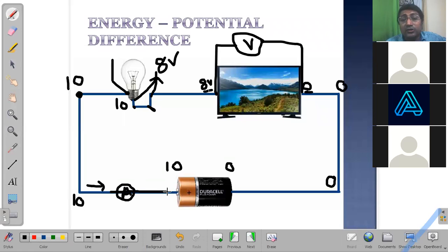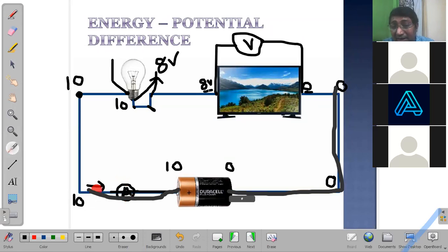Since I want to know, if you remember, the way we understand electric current is very simple. Guys, whenever you hear electric current, I wanted you to understand two things. How fast are the electrons moving? How many electrons are moving, if you remember. So if you want to connect an ammeter to measure electric current in this wire, you have to connect it in series. Why? Because you want the electrons to flow through the ammeter. So that's the reason.